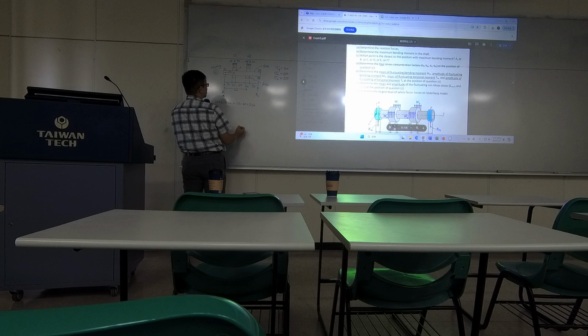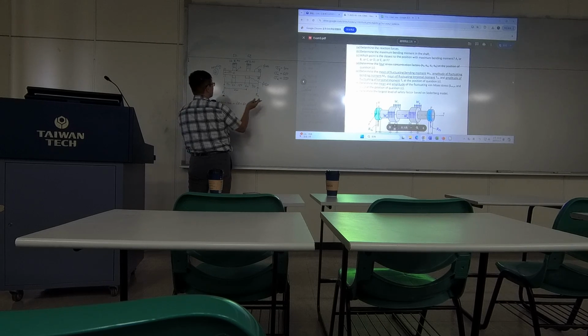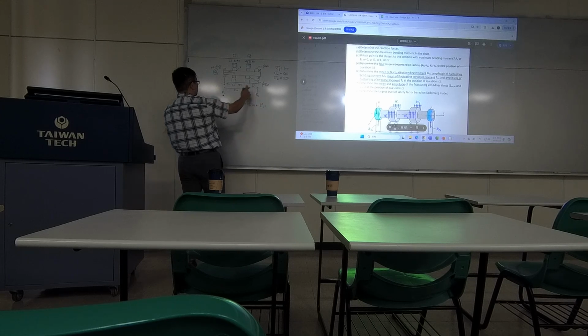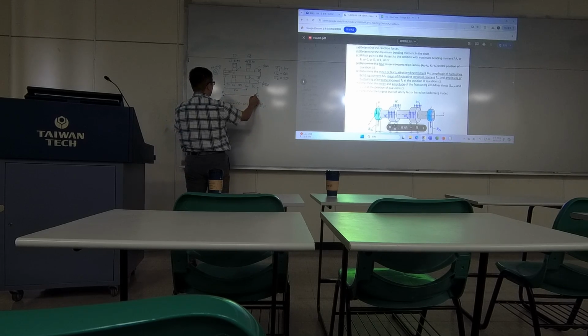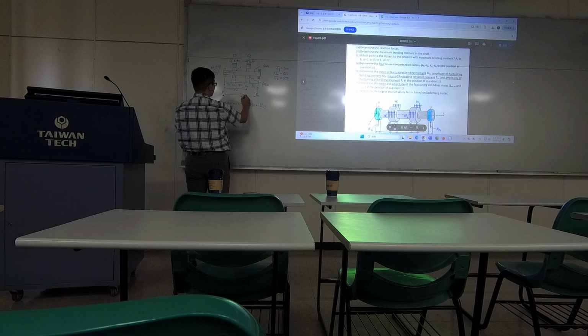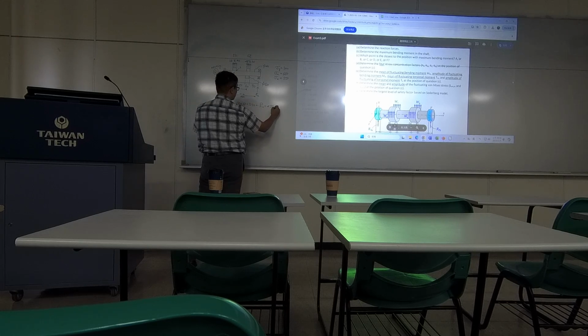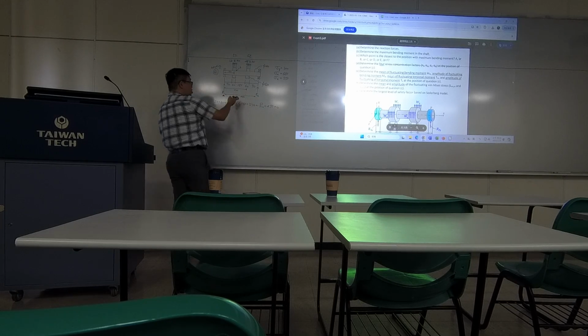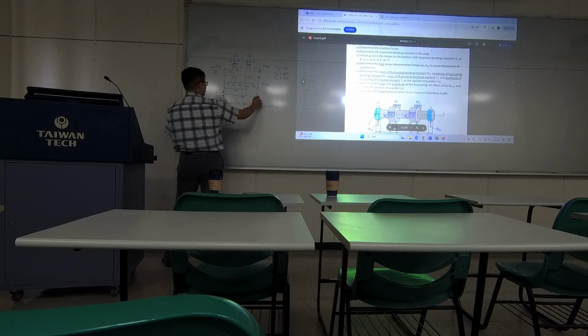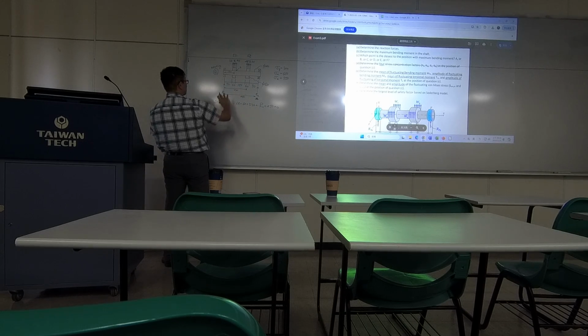Okay. And this one also counterclockwise. So R2 times the total length, total length would be 120, 180, 300, 450. So 450 R2 equals 0. Okay? So this is how you can get R2. And if you put a support point right here, you do the same thing, but this time it will be clockwise.